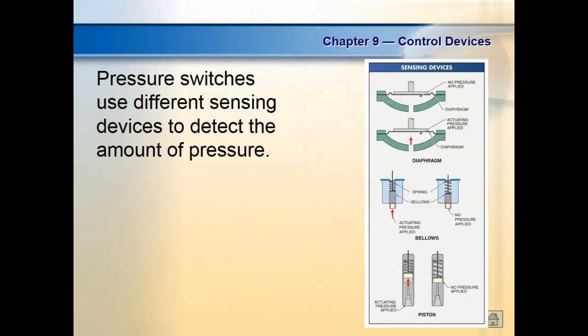Piston, we don't have this one, but we have what we call a calibrated spring, which compresses and extends at a precise pressure. Normally springs are not made accurate, so you might buy two springs like on your pen, and you measure the compression length for one, you go to the next one, it might be different. What we call a calibrated spring is designed to expand and contract at precise distances with certain amounts of pressure or force.